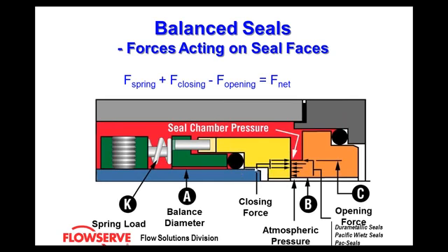This region down here, which is in blue as it interacts with the yellow seal face, is referred to as the balance shoulder. So as you're looking at any mechanical seal, if you see the springs in line with the face, you know you have an unbalanced seal. If you see that it's above, you know you have a balanced seal.